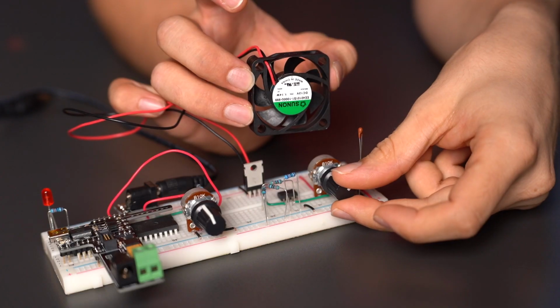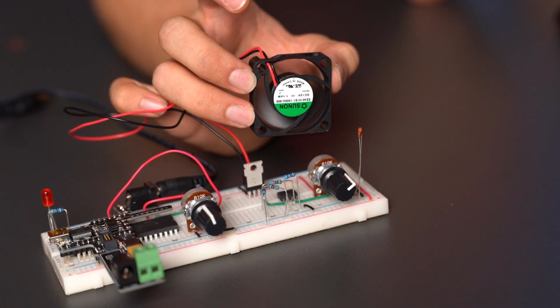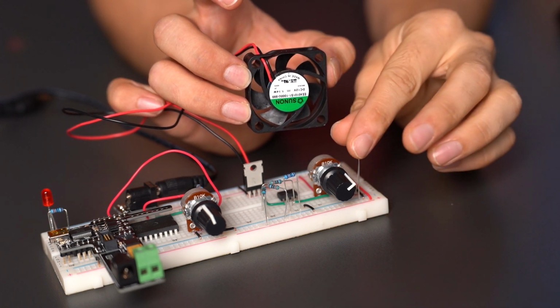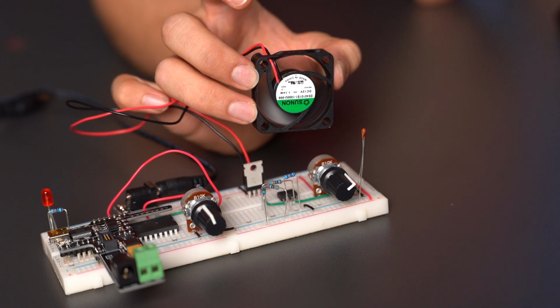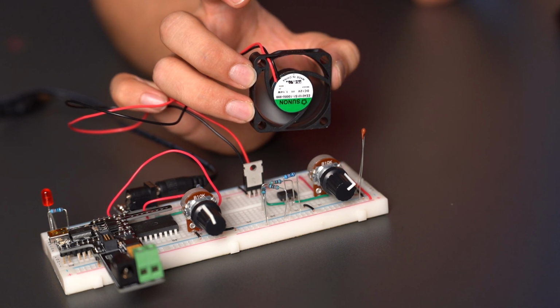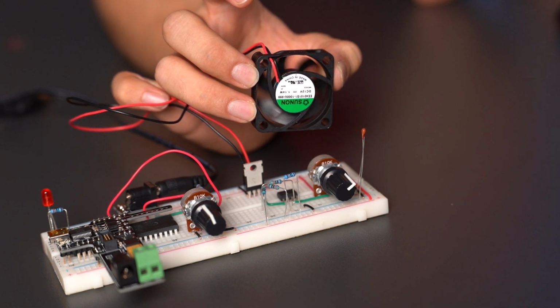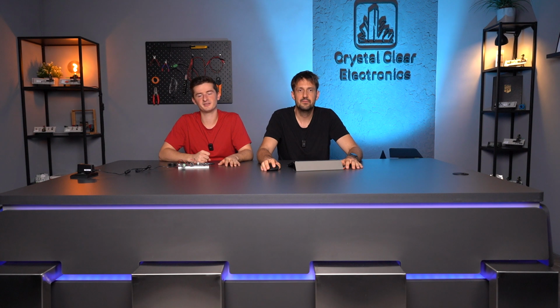You can test the circuit if you adjust the potentiometer in its steady state until the fan stops spinning. After that, if you warm up the NTC with your hand, the fan has to turn on. If you stop warming it up in a short amount of time, then the fan has to turn off again. You can replace the fan with an LED as an example, but don't forget to connect the proper valued resistor in series with it. I think we have learned a lot of new things in this video too.